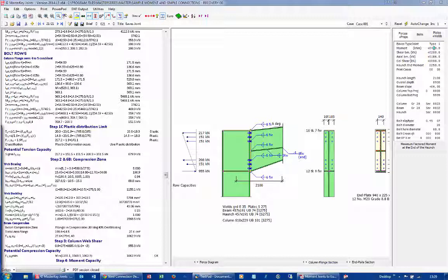And there's another modification factor involved here. We have our old friend omega, which is coming in, and there's also a K factor that comes in to the design of the buckling. And again, it's to do with what we call coexistent compression. So if this was a multi-story member, previously in the BS, we weren't interested in what the axial load here was and how it would affect the compression capacity or the shear capacity of the section.